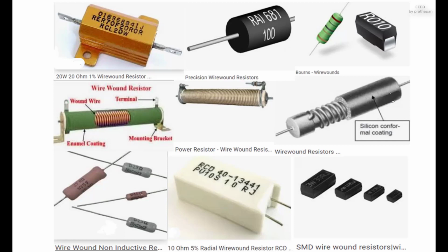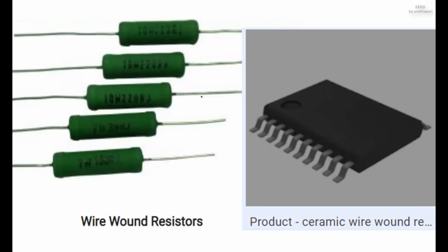Wire wound resistors are coils. They have more undesirable inductance than other types of resistor, although winding the wire in sections with alternately reverse direction can minimize inductance. Other techniques employ bifilar winding, or a flat thin former, to reduce cross-section area of the coil. For the most demanding circuits, resistors with Ayrton-Perry winding are used. Applications of wire wound resistors are similar to those of composition resistors with the exception of the high frequency. The high frequency response of wire wound resistors is substantially worse than that of a composition resistor. Foil resistor.